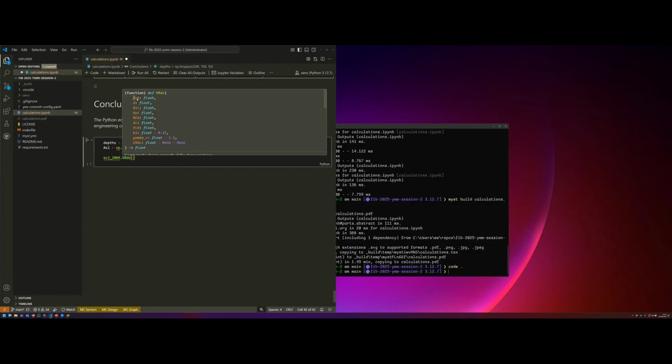So if fck is really the lower fractile that you're entering, or is it just some representative number? If this is actually the lower 5% fractile, then you should subtract 8 from your measurement. If it's just some representative number, why not use the measurement directly in it? And then, of course, the gamma C should be 1.0. Yeah, that's a good point.